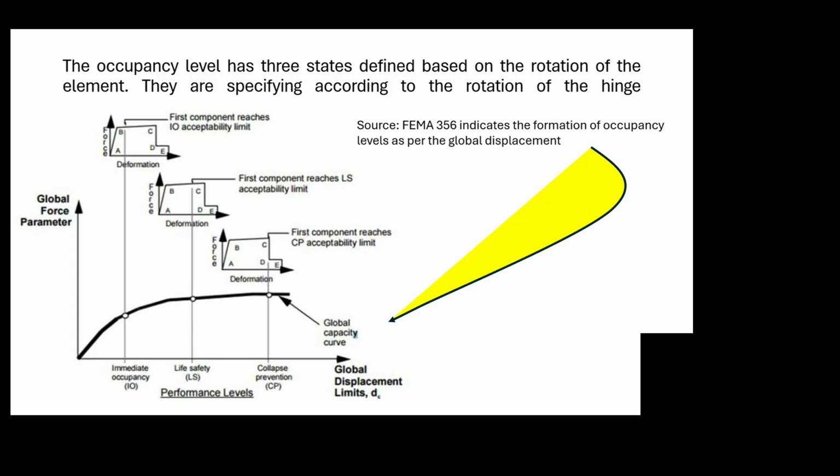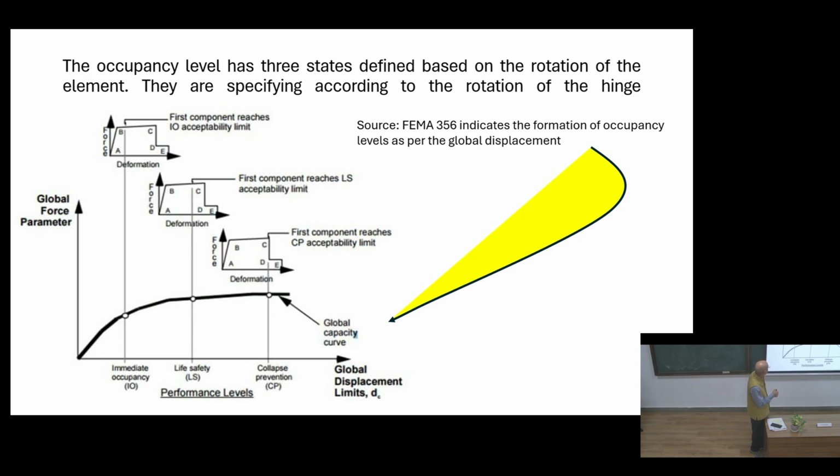Now this plot, I made it. In a couple of slides afterwards I'm showing how this comes into the picture. Professor Datta has mentioned this one. This is an idealized force deformation curve. It's not actual, but this is the force diagram we use for the pushover analysis. So today when we take some example, we are using this sort of force deformation characteristics. Okay.